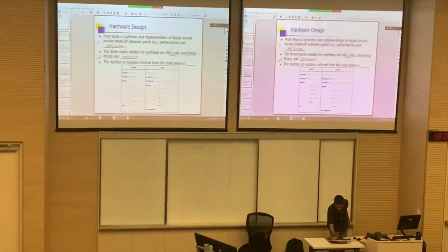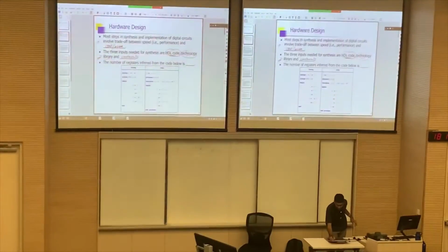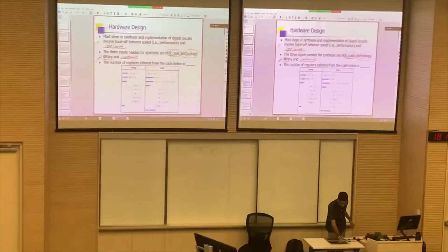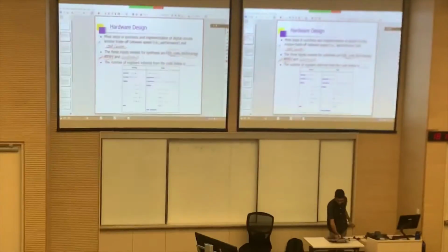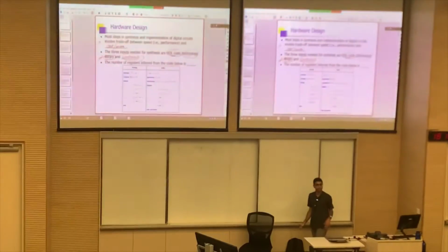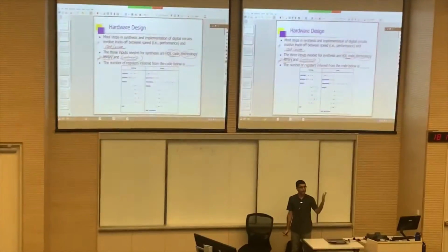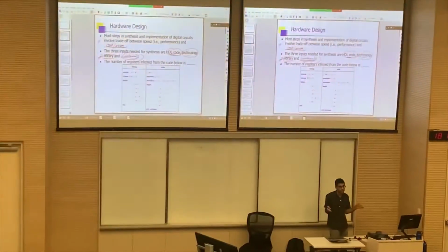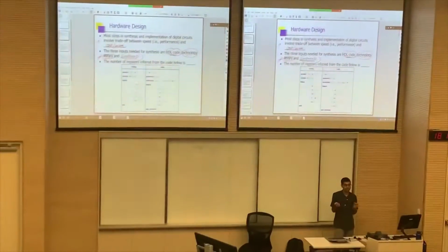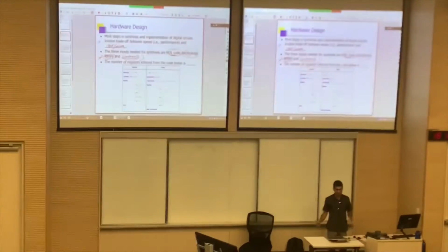So the functionality specified by HDL code is realized using the various building blocks from the technology library while respecting the constraints. And there are fundamentally two types of constraints: timing constraints and location constraints. Timing constraints specify the speed at which your circuit operates, what is the maximum possible delay between a point A and point B, etc.